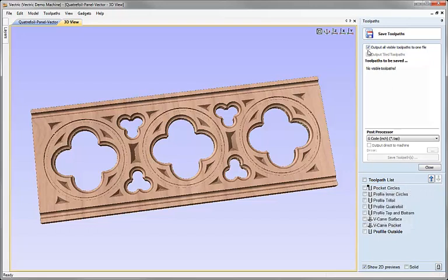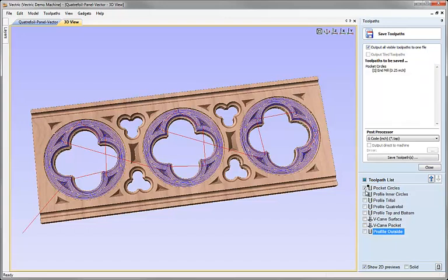So now with this set I could come in and click them in the order that I want them to be saved into the particular file. So for the first two here I'd click the first one, then click the second one, and so the software shows me now those two are visible, that it's going to save. When I hit Save Toolpath, it's going to save a single toolpath.